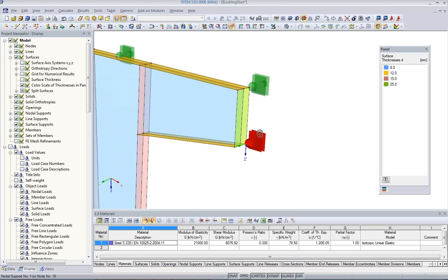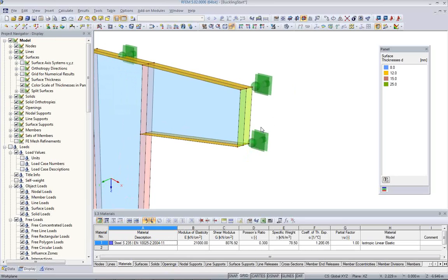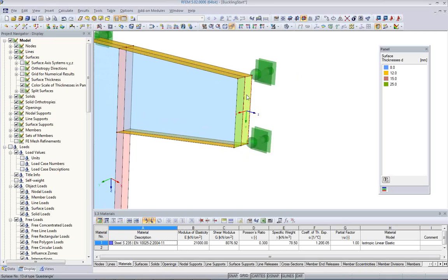But I do here now an individual loading with a vertical load. Typically what you should not do is to introduce the load on one finite element point node. So it's better to distribute the load along the depth of the beam, and the length of this center line here is 600 millimeters, just remember this.